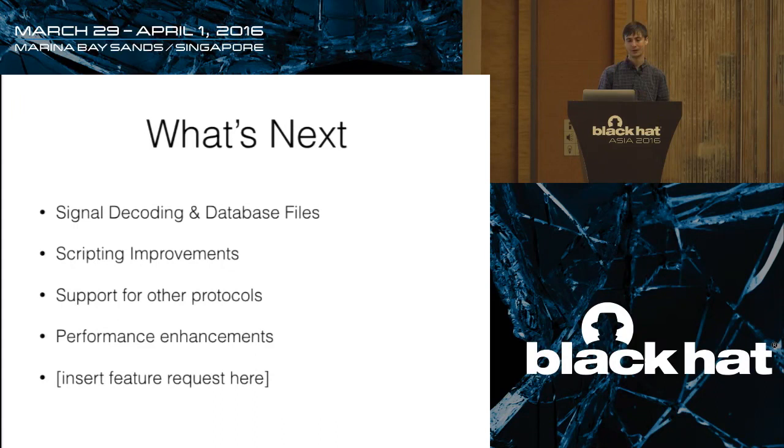So Open Garages is one example of an organization that's trying to spread more information on this type of stuff. They also have a collection of, here's an Excel spreadsheet of signals we've found in this particular vehicle. There is one open format, which is the Kayak format for defining all the messages on the bus. No one really uses that except for that Kayak tool. The traditional one is the DBC file from Vector.